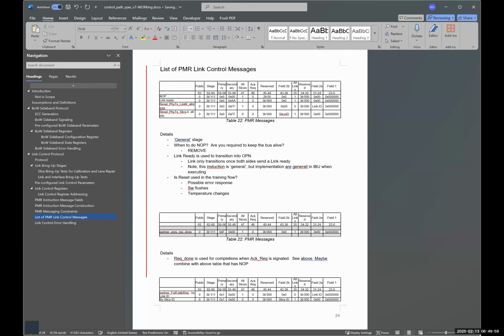Again, this is implementation specific. I had a data link layer state machine that would track all of these. But in the absence of a data link FSM, if one side goes down, the only way to let the other side know that I'm going to start my training again is via the PMR, because the PMR is expected to stay on all the time.